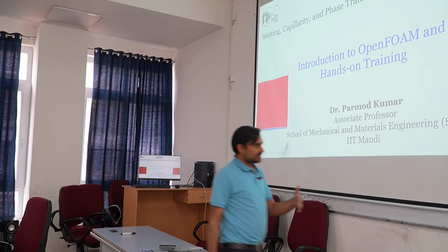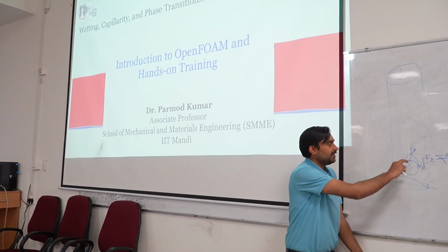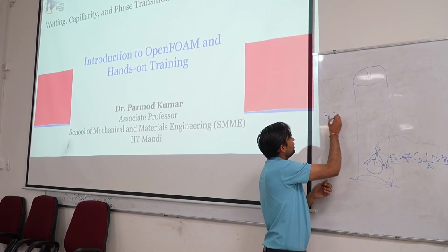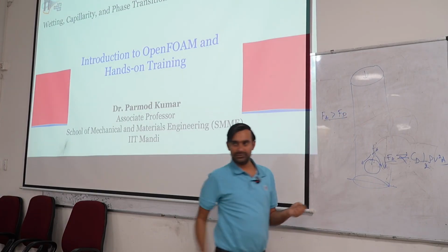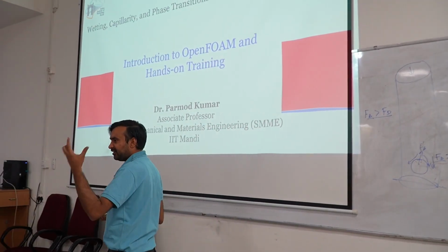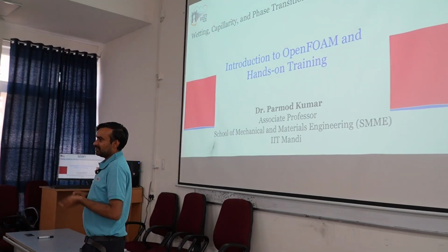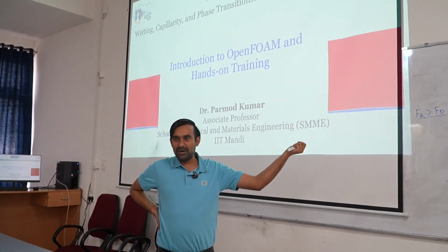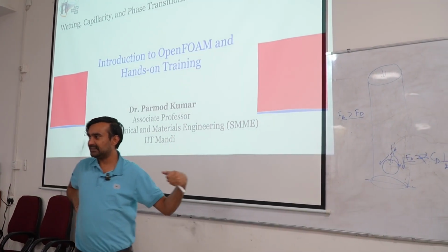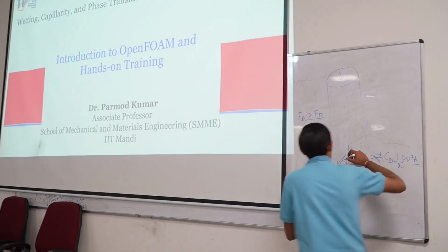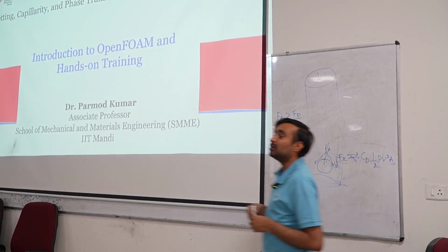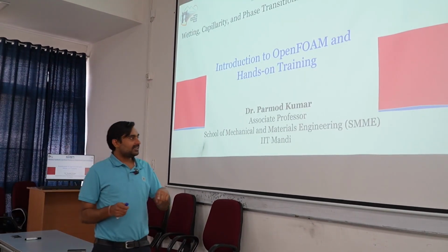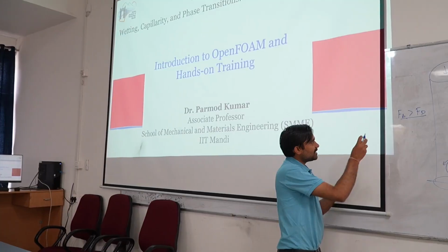Once it has started rising, its velocity will keep on increasing, because initially the buoyancy force is greater in comparison to the drag force. If the force which is driving is of larger magnitude than the force which is restoring, in this scenario we will find that the bubble will accelerate. What is the meaning of acceleration? As it starts moving in the upward direction, its velocity will keep on increasing. But when the velocity is increasing, parallelly what is happening?